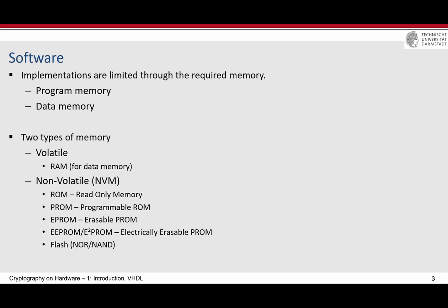The program memory, no matter whether it is a microcontroller or anything else, is usually non-volatile memory. For example, you write the program of your microcontroller into NVM, where flash is the current technology. Then of course, when the power of the board or the circuit is gone, the data stays there. With the microcontroller, you write the program memory in the flash inside the microcontroller, or even sometimes outside. And the same actually applies to FPGAs.